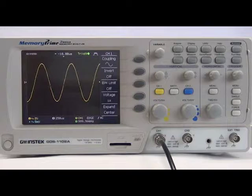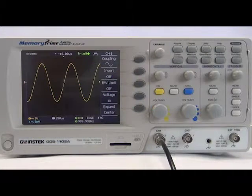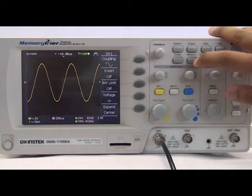Task 4.2 is to measure the input signals using automatic measurement function. For this procedure, we have to find four components, which are RMS voltage, peak-to-peak voltage, period, and frequency. To obtain the RMS voltage on the oscilloscope, press the measure button.